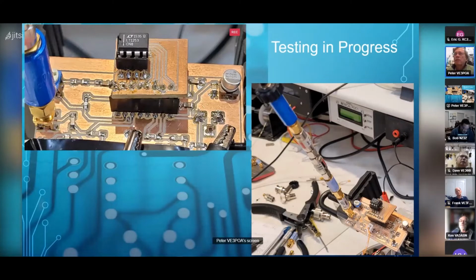And on the left is just a closer up view of what I was talking about, where the breakout board for the 1253 is over top of the pot that's sitting underneath here. And there's the other pot over there for the adjustment for the first stage. And like I say, I was using pin headers there for the RF out, which, as you can see, is not probably a very good idea.